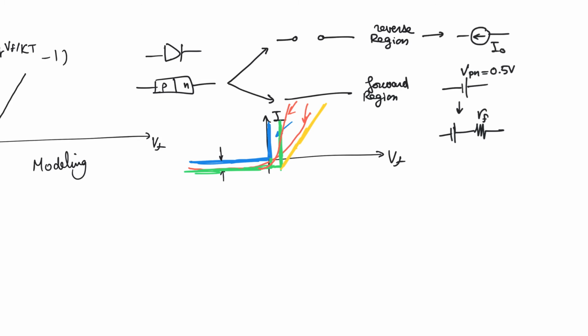And because it's easy, it allows you to do some back of the envelope calculations really quickly and allows you to understand how circuits work really quickly. Now, when you need to do a more involved calculation, or when the application depends on the forward resistance, you perhaps need to use the model which uses the forward resistance. It's going to take more mathematics and more work to solve problems when you have forward resistance, but perhaps it's needed for certain applications. In general, when we talk about semiconductor devices, it's advisable to use a model that includes only as much detail as needed.